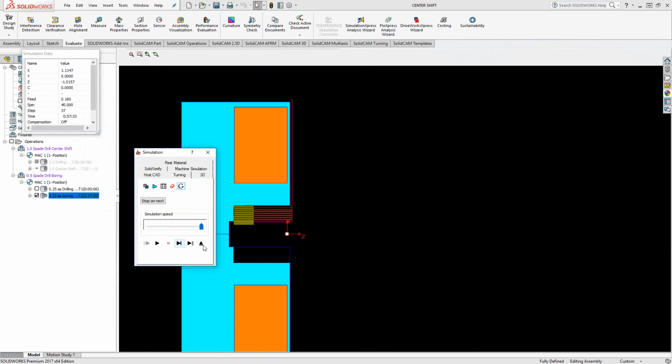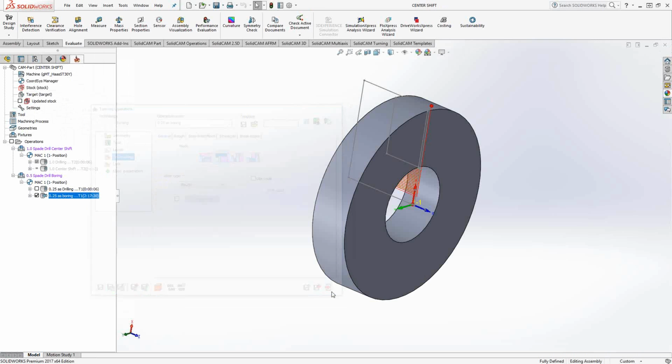Okay. So how is all of this possible inside SolidCAM? Well, it's really more on the tool definition side, because as you saw, the operations themselves, the toolpaths themselves, are just the same as you've always done: drilling and a turning cycle. The only thing different in terms of the toolpath is the center shift. If the tool, the insert drill, is large enough that you can get away with doing just a simple one pass sort of tool path, then we can do a center shift.